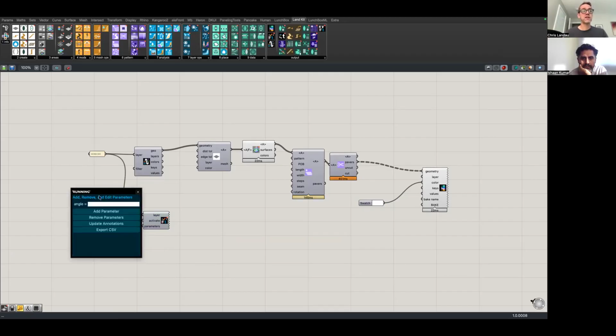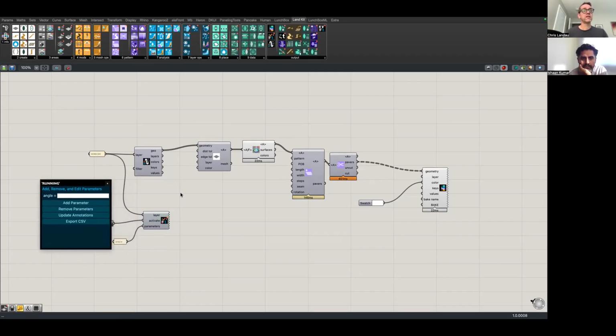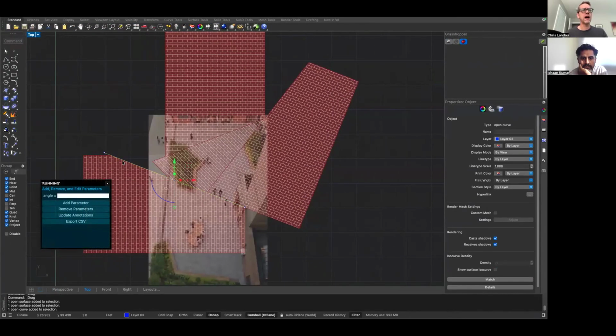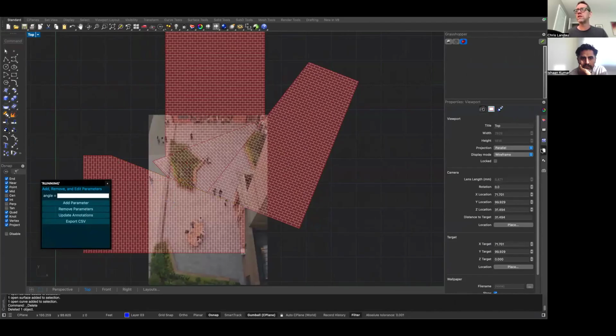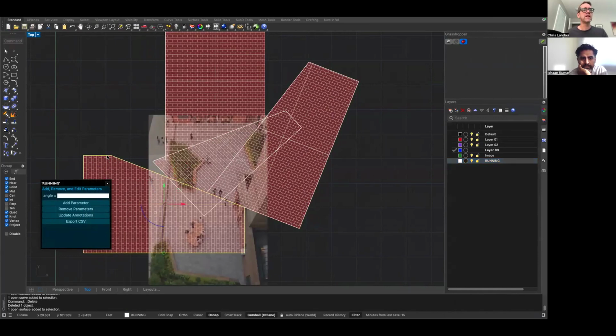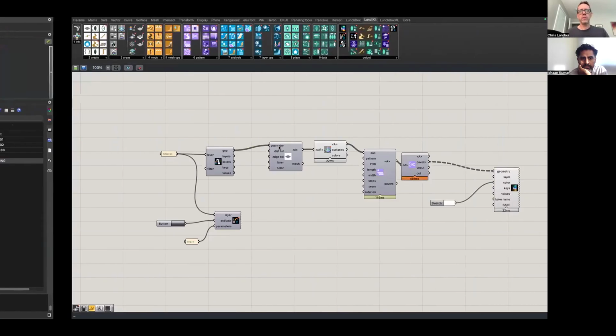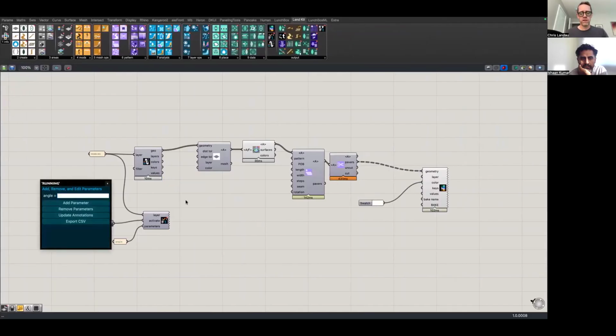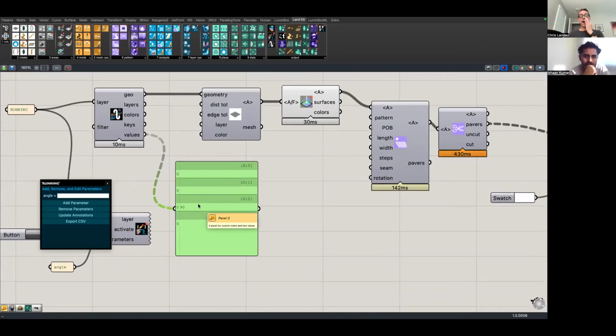So when I click on this, based on this running layer, it's looking for stuff on that layer. So if I select this guy, oh, not the curve, the surface, you have to turn that layer back on. So when I select this guy, I might say, well, actually these need to run this way, right? So I'm going to give it a 90-degree angle. And the rest of these don't have values. They're just blank for now. So then when I look here, what is coming out of my geometry when these things are being brought in? I have keys, which is the angle, and values, which is either nothing or 90, right? So now I have data associated with each shape that I can use and do things with.